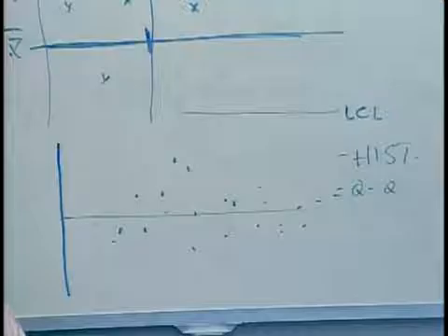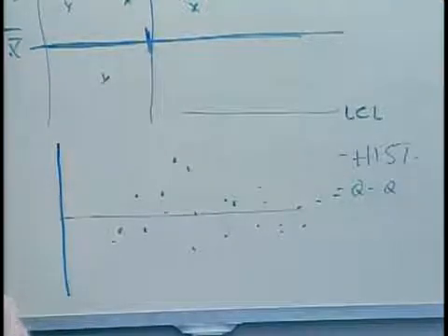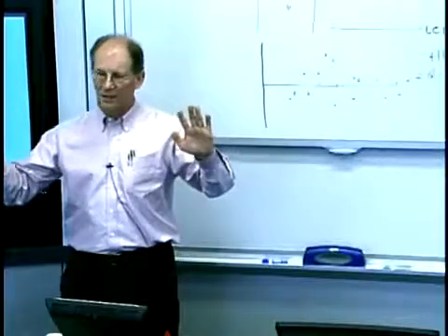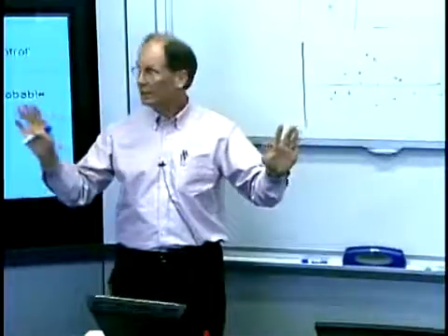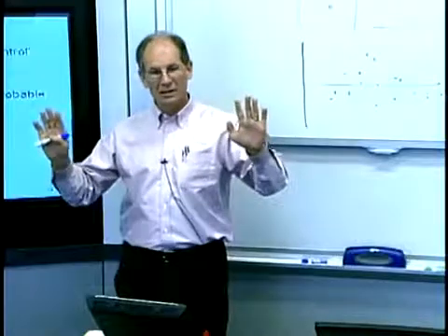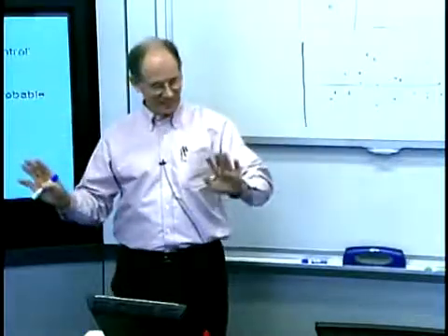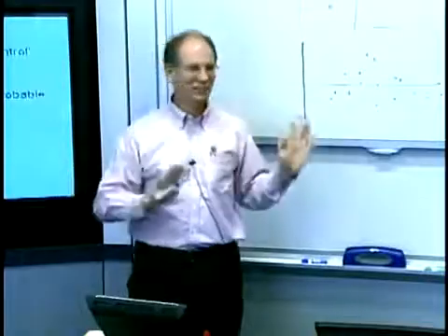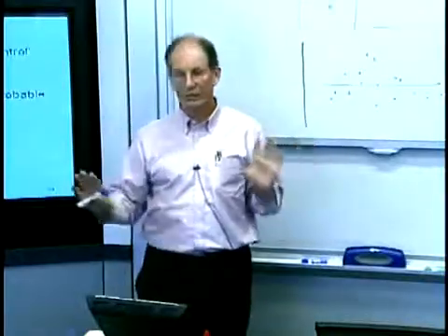What else? Hayden, what else could we do? Well, I'm thinking you could get the upper and lower control limits directly from your specification. You haven't done any work. Yeah, be careful with that, though. Good point. That's the same issue. Here's what I expect it to be, but the whole point about process capability, which I'm going to get to in the last 5 minutes, is that process capability is what you're dreaming of getting. This is what you actually get, and they could be really far off.